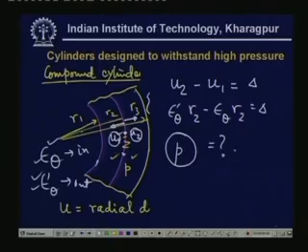So, this is quite an easy exercise if you follow these steps. What we have learned is that here we can take large pressures, remember, because of the compressive stress developed in the inner cylinder, a large pressure could be withstood by the inner cylinder because there was initial compression.